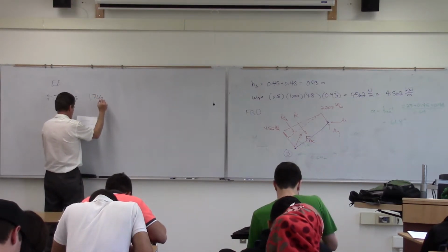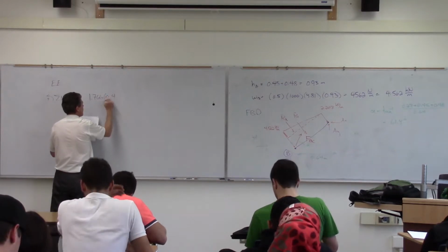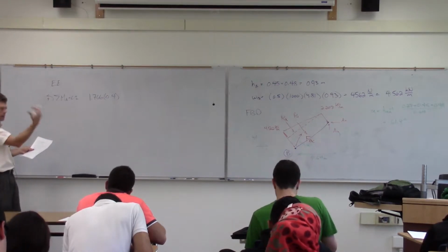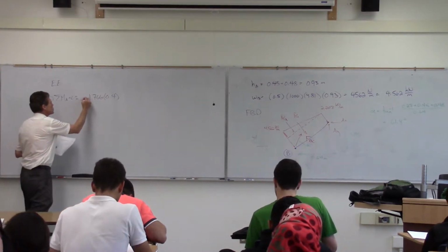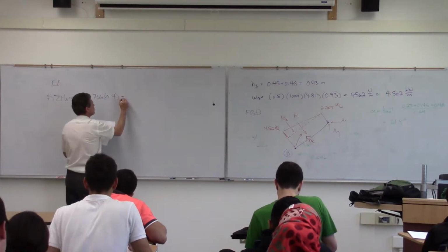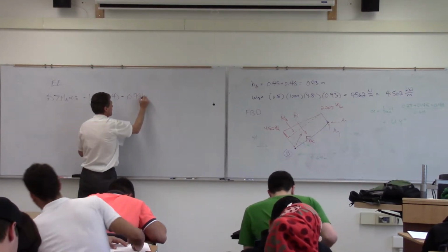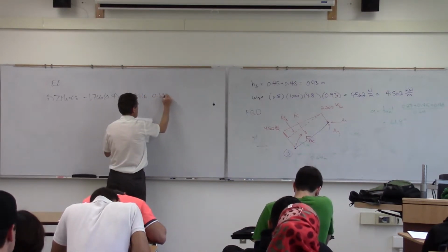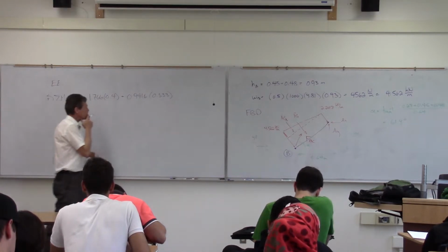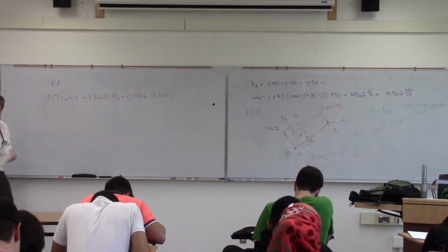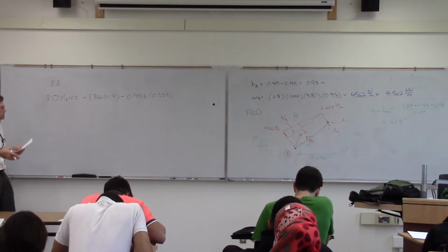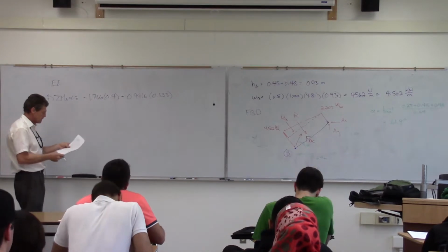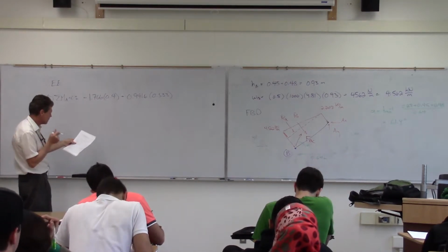Our rectangular area, and we think about A there, it's going to want to twist me via right-hand rule in a positive sense, as will the other portion of the water. So that's my two components of water. Again, I could resolve them to one, but at this point in time, equilibrium is much easier in terms of just simply adding the extra term, instead of spending all that time creating a single resultant.